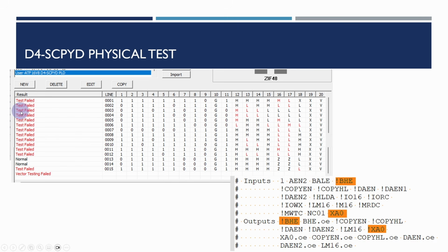What eventually I managed to get to the bottom of is that when looking at one of the other files generated, a Berkeley format output file that's generated by CUPL, that indicated there are a number of the pins here which are both inputs and also outputs. And in fact, the problem worked out to be that on some of the more complicated chips which have an output enable term, when the pin is disabled, some of those pins can actually act as inputs.